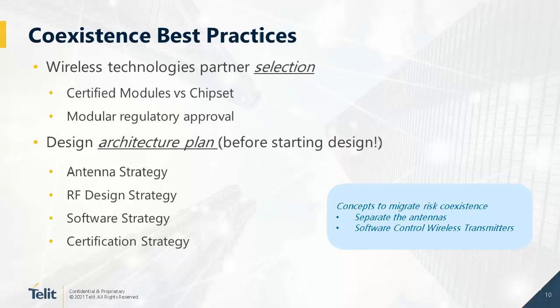I think that's one of the best ways to help reduce risk and ensure you launch a product successfully: making sure that you use a pre-certified wireless module with modular regulatory approval. We can talk a little bit more about that as we get deeper into the presentation. And then obviously the design, right? Before starting your design, we have to understand, are we going to fight the coexistence challenges or are we not? Again, this will impact everything from your design strategy, from antenna, RF, software, and certification.